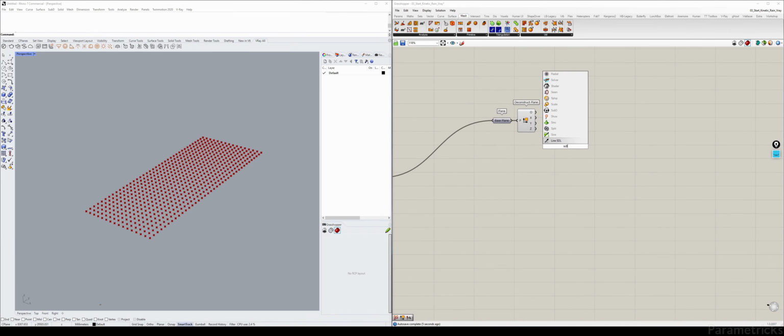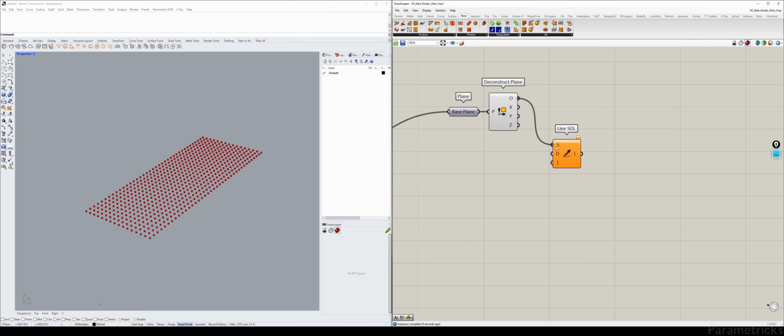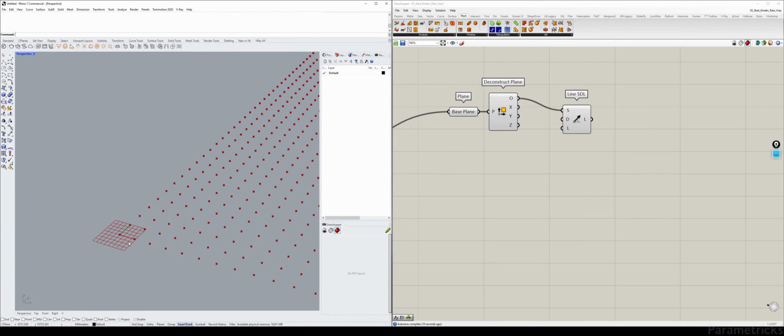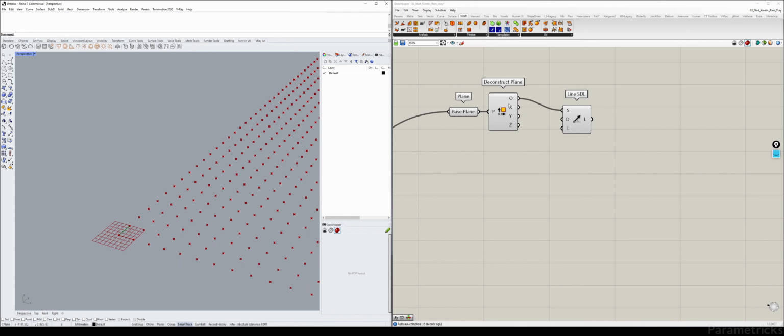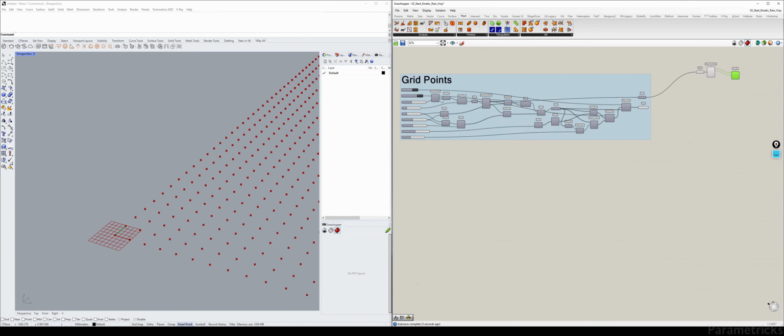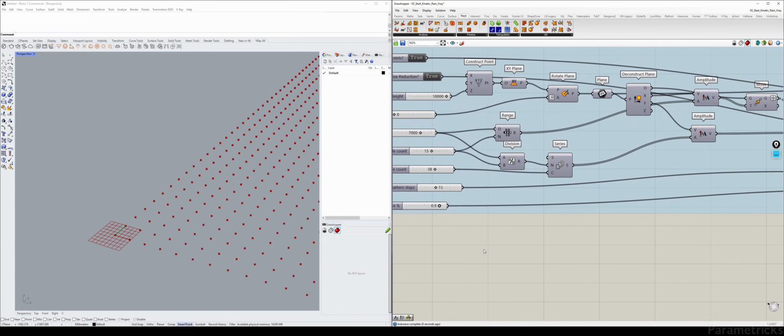A very easy one is to just do it as Z L. We know the origin is there. Now we need to figure out which one of these do we want. So if I turn that base plane on, we know that the red axis usually indicates, or actually always indicates, the x-axis. So we know that that's the direction we want to go. So that will go here. And as for the length, well, the length just so happens to be the width. So we can actually make a number. Yeah, we'll make this a number. We'll take this one here.